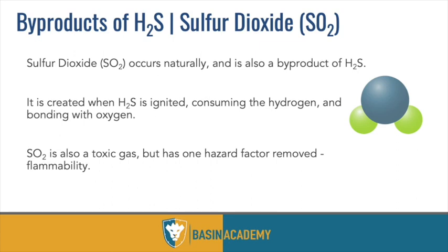You get SO2. Benefits of SO2: it's a little bit less heavy than H2S, still heavier than air. The flammability is gone, so now we're dealing with just a toxin instead of a toxin and an accelerant. So that's another benefit. And then thirdly, you can detect SO2 even at higher concentrations because it burns your nose, much like a match would after it's been put out.